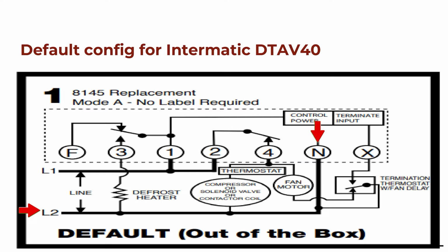L2 is coming in, landing on N, but this could actually be neutral if this were a 120 volt system, which I don't know how common that would be to see, but certainly, refrigerators in our homes are a self-contained system, 120 volt. Those probably have microprocessor type systems in them, but it could be controlled by a mechanical system like this as well. So that could be neutral. But you could think of this as neutral or line 2. Either of those would be fine to think of in this type of time clock.